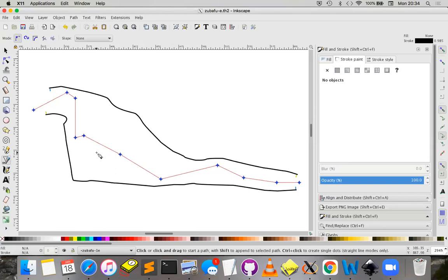Let's select the Bezier curve, disable snapping, and draw our pillar. Now, usually in Therion, in order to draw the walls of your passage, you draw in an anti-clockwise manner. And the opposite is true if you're drawing a pillar. Therefore, we shall draw in a clockwise manner. Click and drag.